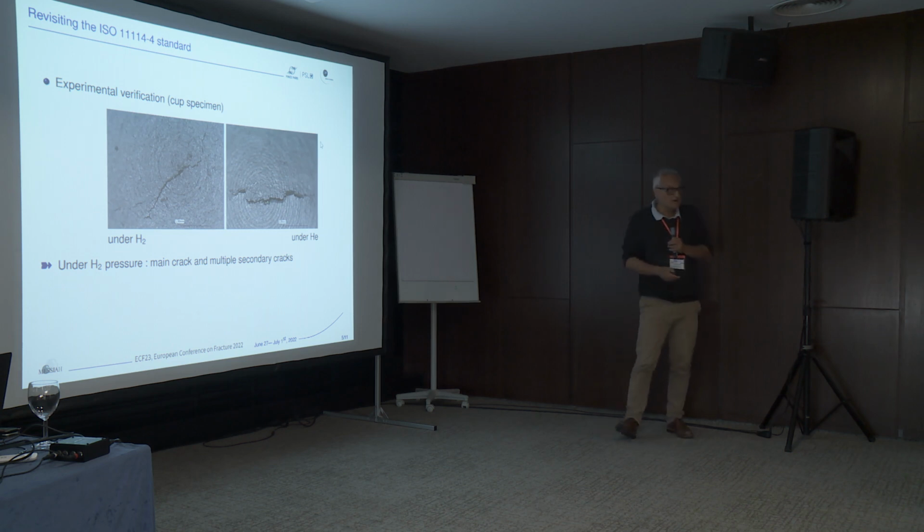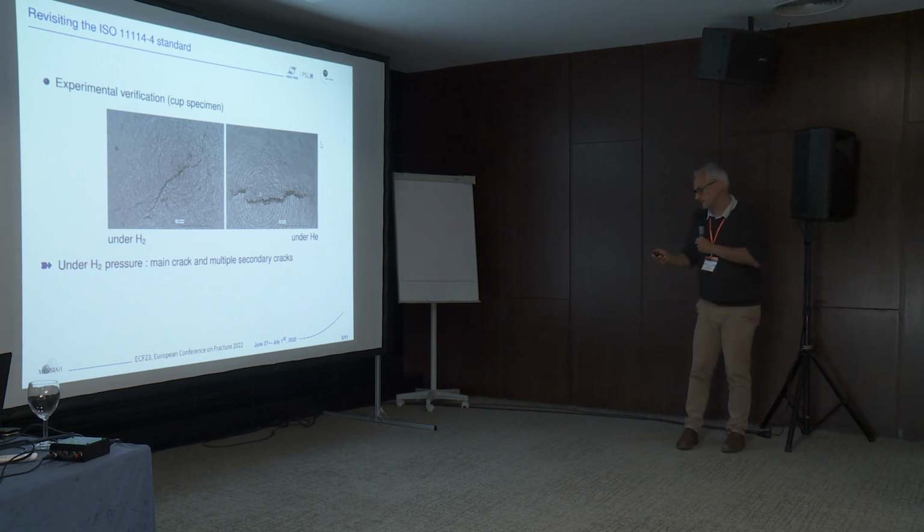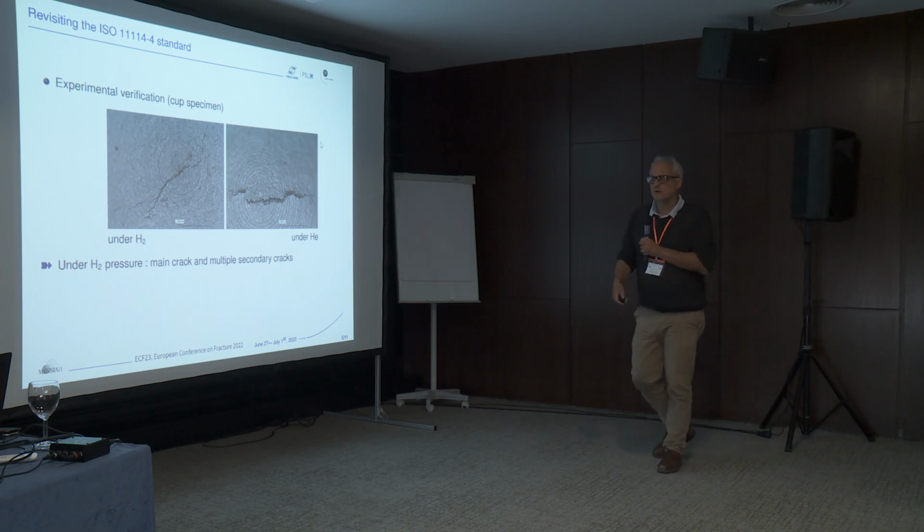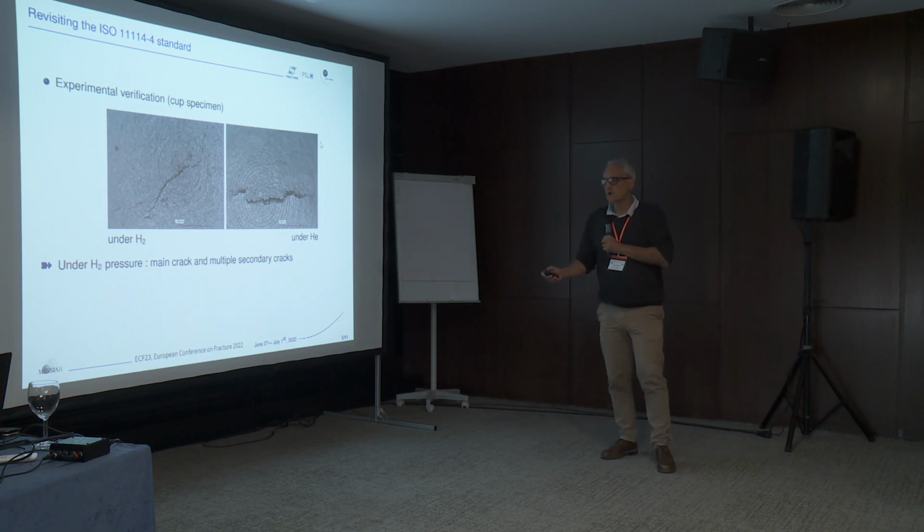We did some preliminary experiment with the design, and here are the fracture, the crack on the surface of the specimen when the specimen leaked. So under hydrogen, you see this crack on the pressurized side, but you see also secondary cracks, which is a good sign that fracture was initiated on the pressurized side. So we're happy with that.